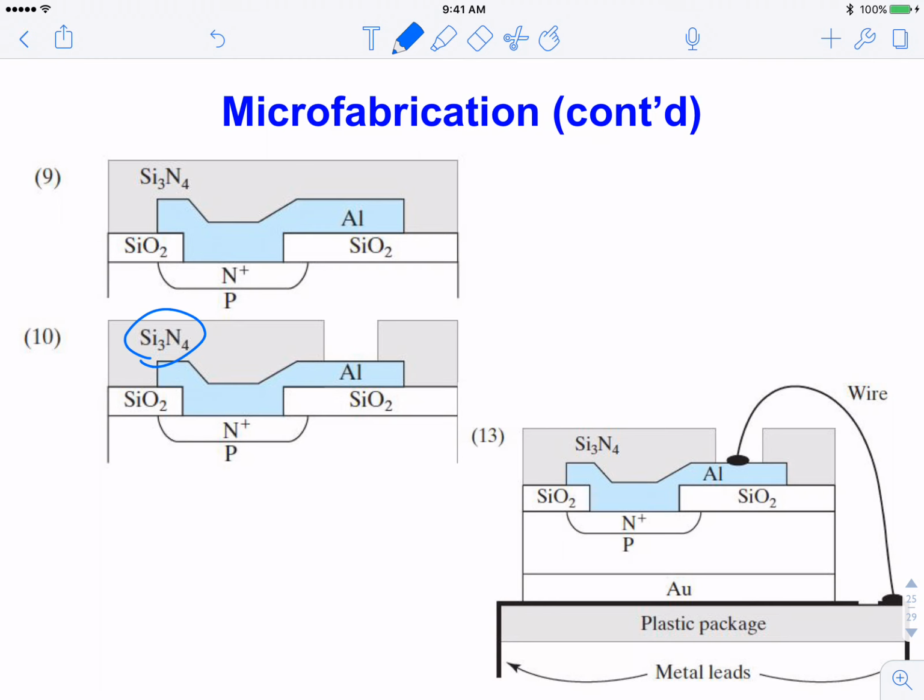For example, the photodiode in your lab 3, basically this is the process. You have a photodiode. This p-n junction is sensitive to visible light for silicon. You have a p-n junction diode. You need a bottom contact, so you need the metal here. This example says gold. Gold is actually a forbidden material in the fab. Gold causes defects, deep level defects.